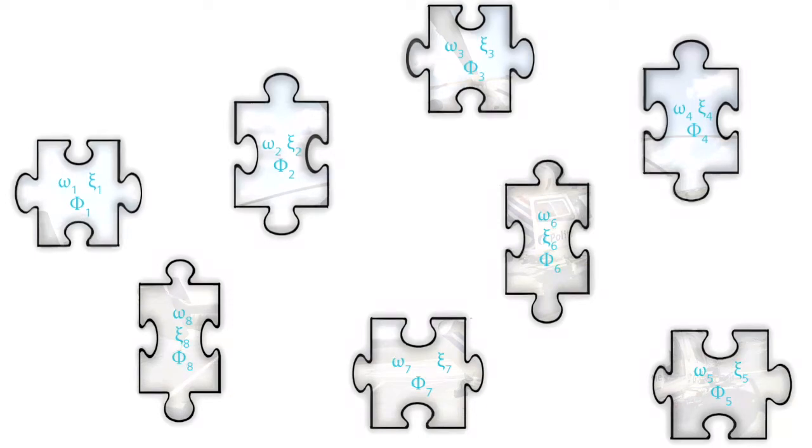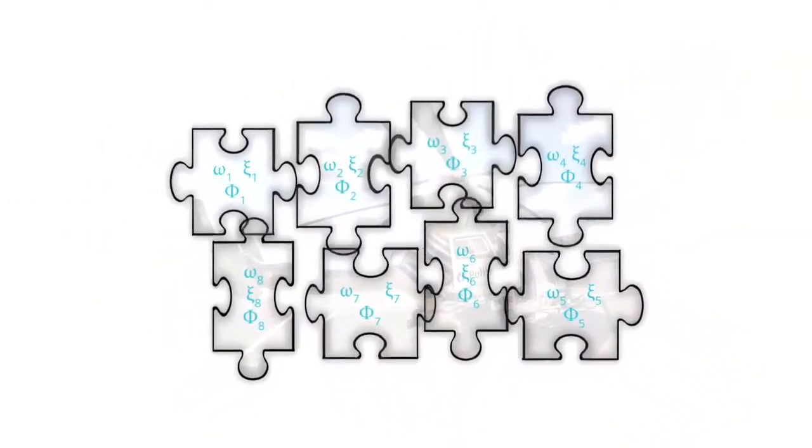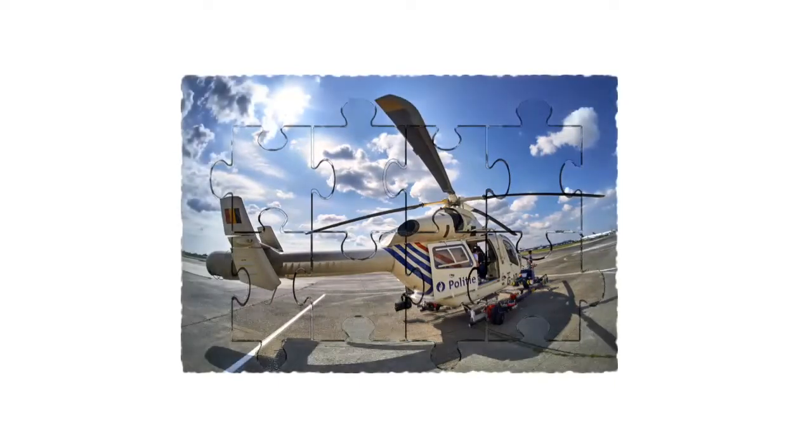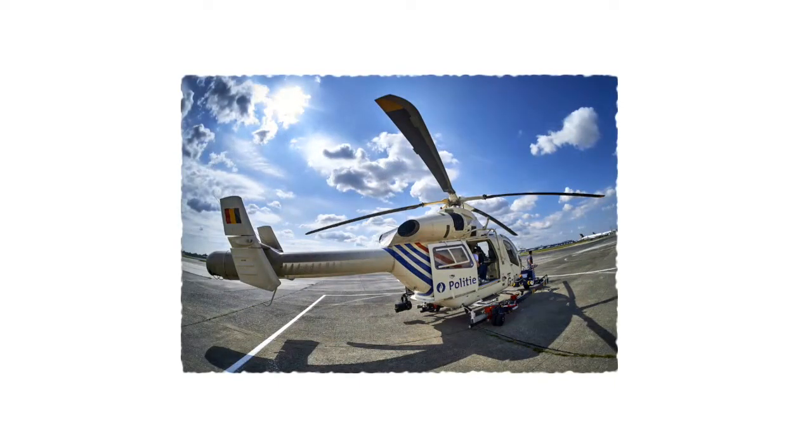Real structures have an infinite number of modal parameters, but in practice we can consider a finite subset, which will depend on the frequency range we are interested in. The modal parameters, which can be looked at as independent elements, can then be combined together into a modal model, which represents an equivalent and practical description of the complete structure. They have the very important property of being independent of the applied load. They're simply a description of the structure.